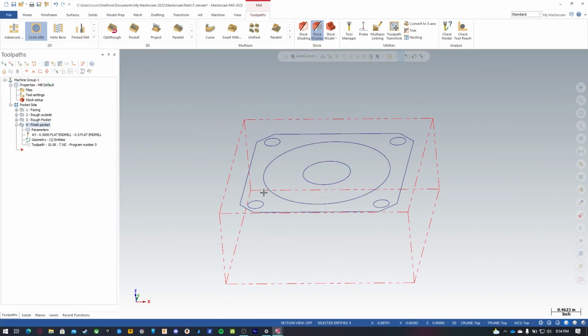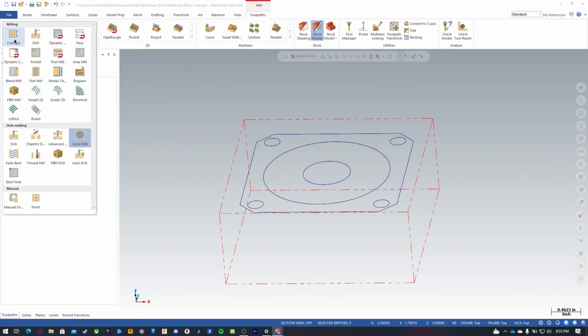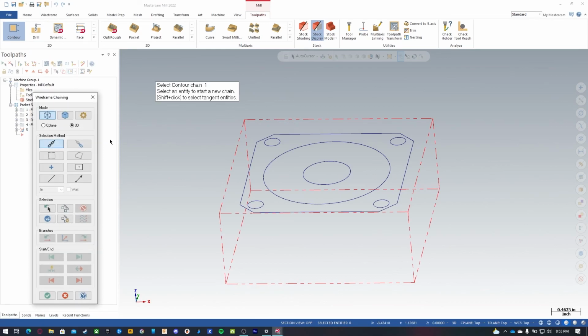So now we'll turn off the toolpath and collapse it, and now we can do our contour toolpath for the outside portion. So it's important to figure out which direction for climb milling. It leaves a better surface. If you click that red button, the unselect, make sure you pick the proper side of the line, and that will give you the proper direction for climb milling.